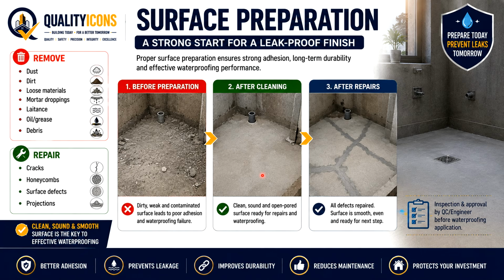Later, the coating can peel or debond. A simple QA/QC rule is a clean, sound, and defect-free substrate first, then waterproofing.